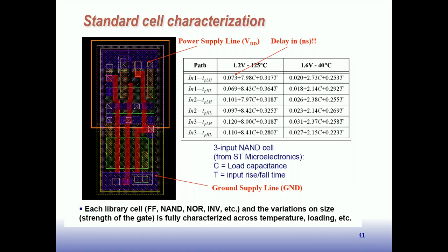It has to make a guess at what the wire capacitance will be until there's a layout that's generated. Right? So early on, during the logic synthesis process, it may just estimate what the wire capacitance will be. Once you push it through all the way to get the layout, then you can take that actual capacitance information from the layout, put it back into the simulator or into the timing analyzer, and do a second pass of analysis with information from the actual layout. That's called back annotation. You take the actual physical layout information and bring it back into the analysis, either static analyzer or into the simulator.